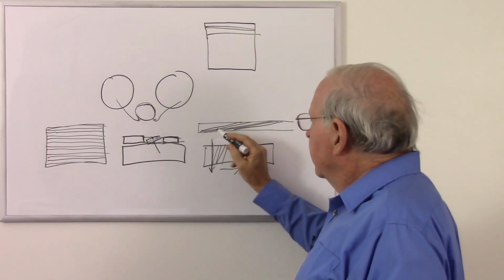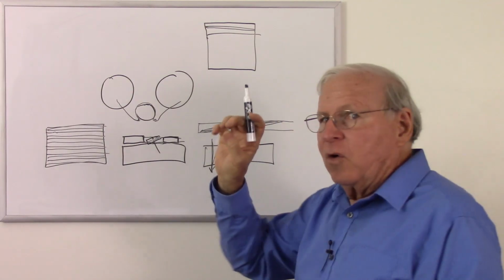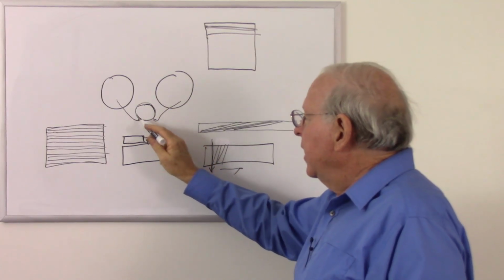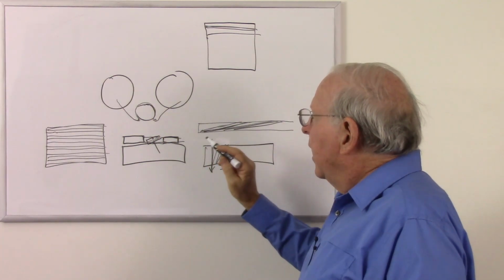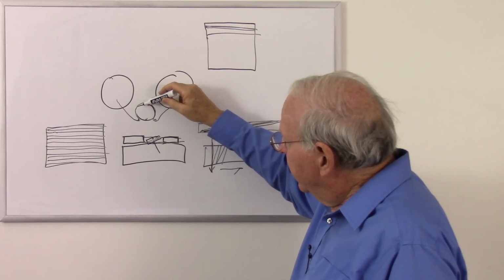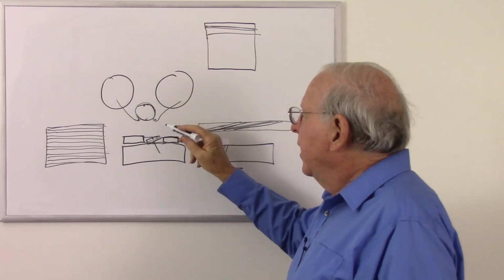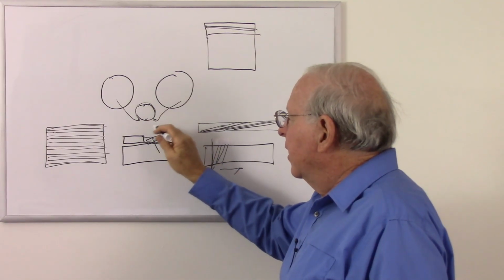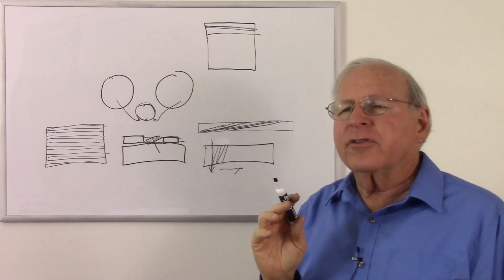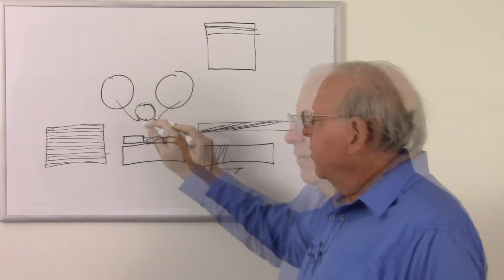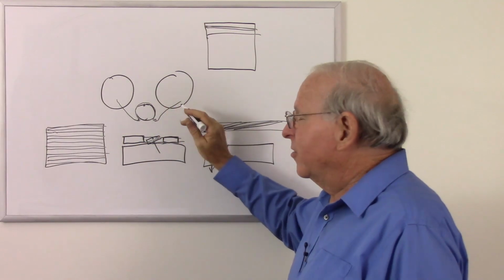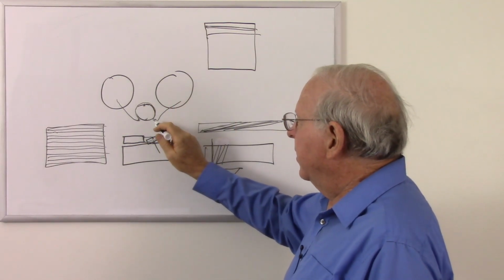So the track on the tape would carry one line, so it would be like an even line, and then it would go again and scan the odd line. And some of them had two heads, although it didn't have to be this way. Cheaper systems had one head. And one head would scan even line, odd line, even line, odd line, even line, odd line. I know that I saw a system in the early 70s where it had only one head and only scanned the odd lines. Didn't even bother with the even lines. And so it was half resolution vertically, basically.